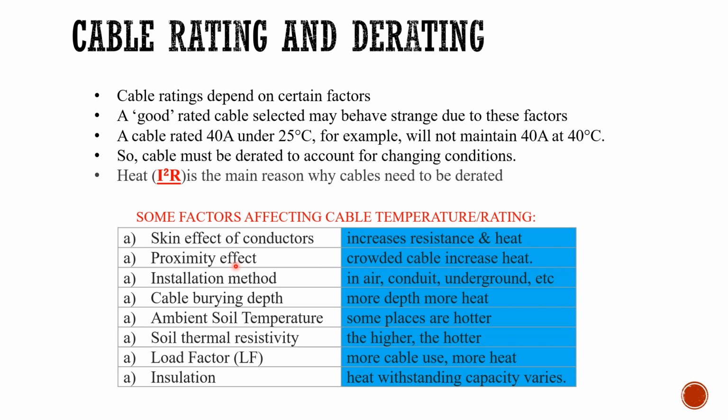Another factor is proximity effect. When there's one conductor inside a conduit system or buried, or whichever method you are using, the heat will be less. But if you have two conductors, three conductors, the heat will increase. So the more the conductors, the greater the heat, and the skin effect also contributes to this.